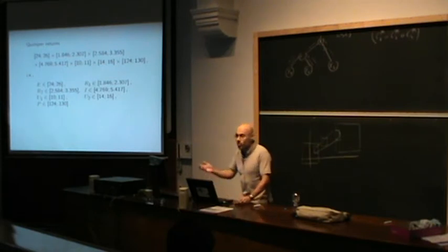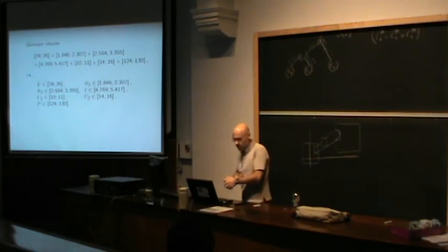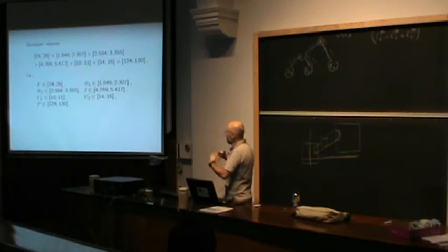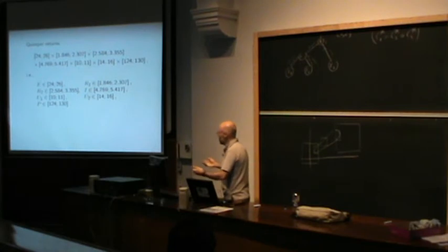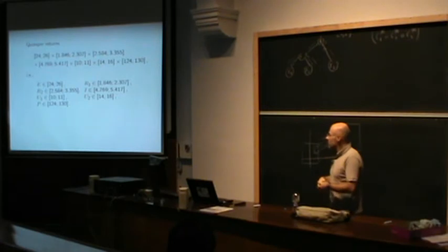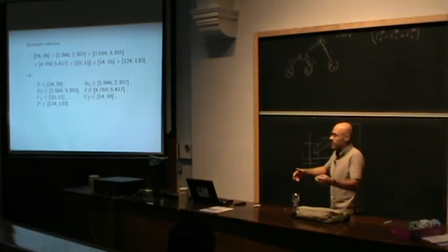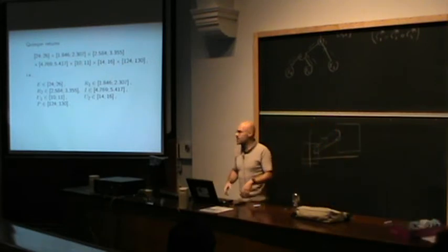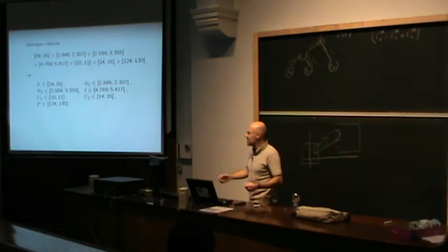Just to illustrate how in practice we use a contractor approach. What is important, if I want to have optimal contraction, is to have redundancy in the equations. So most of the time I need more equations than unknowns, and it will be the case in robotics because we have a lot of sensors. A typical application in robotics is localization. You will have cameras, you measure distance, you know you are in the water, for instance.